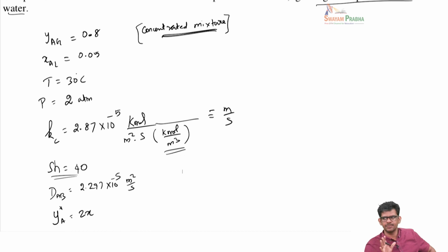All the relationship we have given in the class. So essentially you will have access to the local coefficients in terms of mole fraction units. If you know that, you know the bulk concentrations also. So then you should be able to calculate the interfacial concentrations. And if you know the interfacial concentrations, then you can calculate the flux. So that's the roadmap, that's a plan.